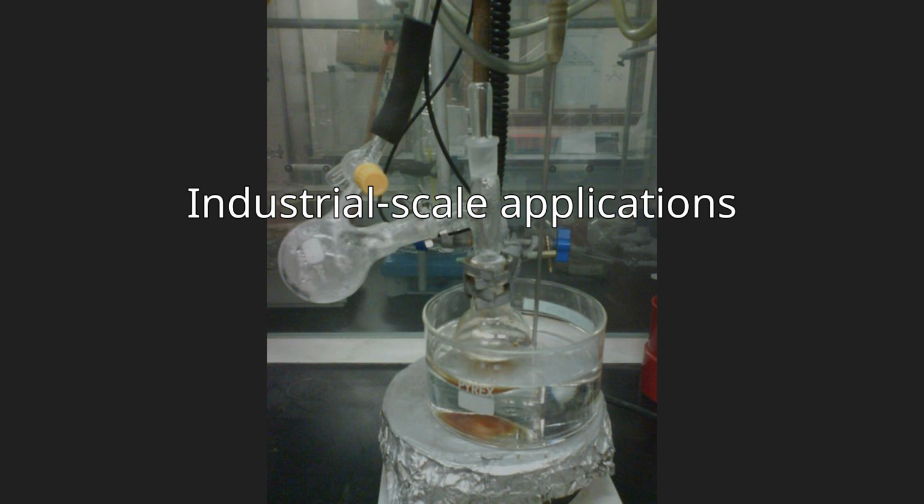Another advantage of vacuum distillation is the reduced capital cost at the expense of slightly more operating cost. Utilizing vacuum distillation can reduce the height and diameter, and thus the capital cost of a distillation column.